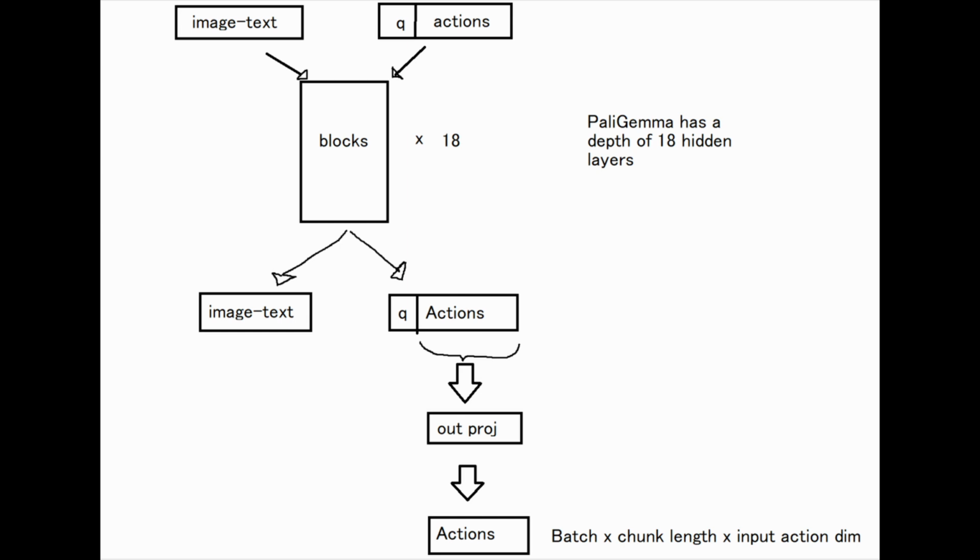Inside the model, it's a mixture of experts-like architecture where the actions, proprioceptive state, and the fused image-text inputs go down different streams to where they'll be attended by their own experts. But during the attention layer, the action representations get to attend to both the vision language model representations and the proprioceptive state to know what information it is conditioning the vector field on.